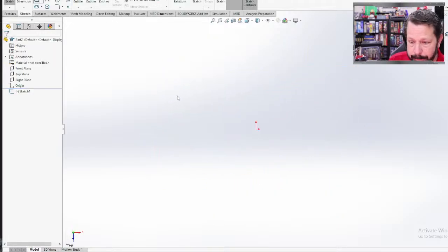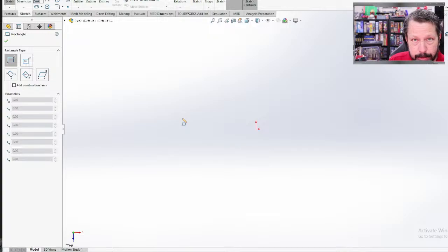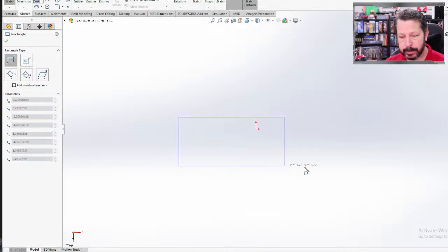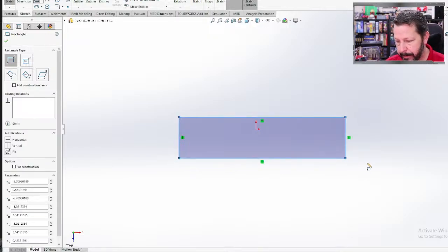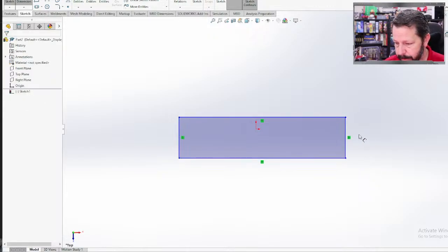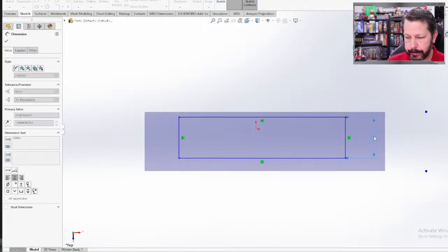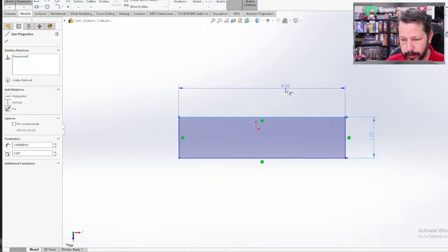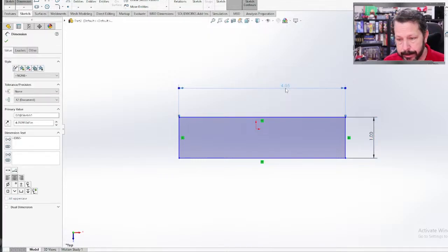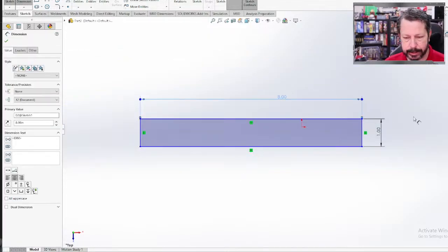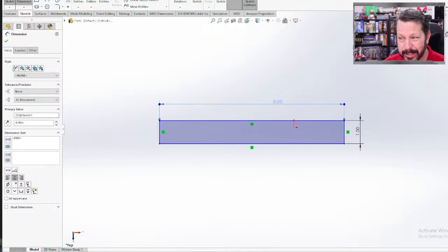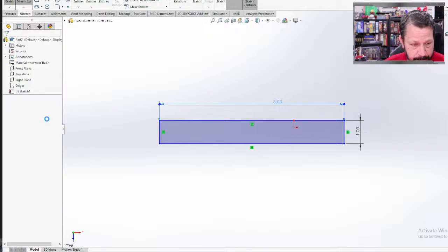And it's just going to be a rectangle. These are not fancy dog bone shapes like the tensile test. It's just a little rectangle. I'm pretty sure I am in IPS, inch pound second unit system here, so if I am, then this is like 1 inch. This is usually somewhere around 8 inches depending on your machine, and then the thickness is some ratio of these numbers. I'm going to say it's 1/8 of an inch thick.